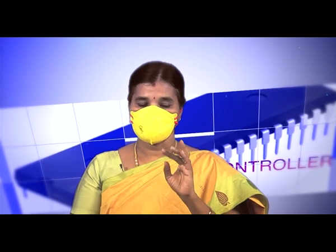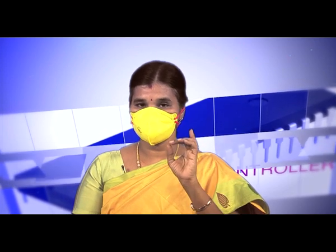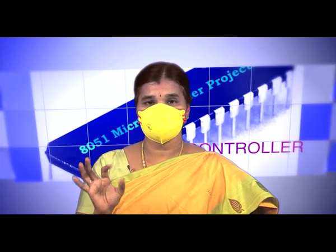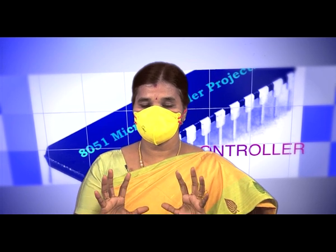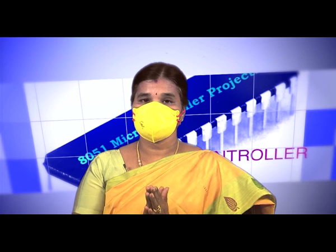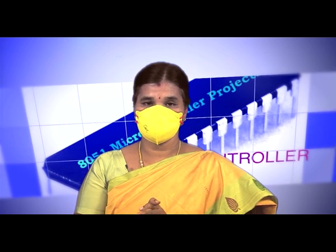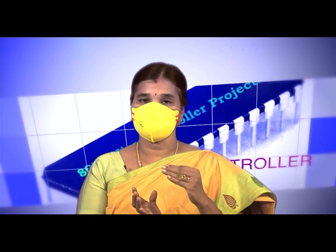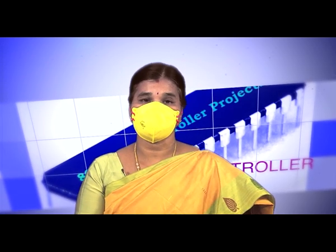It needs the address lines, the data lines, and the type of operation, whether you want to read or write. This is a single IC, so every IC should be selected by some signal, which is CS bar. So in total, only 5 signals are available in each memory. The address lines are a group of unidirectional signals to specify the location. Based on the number of address lines, we can define the capacity of the memory.